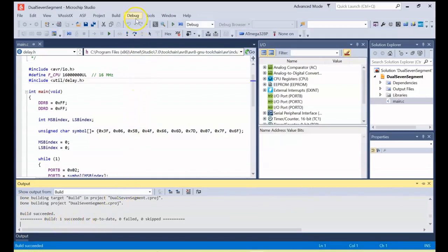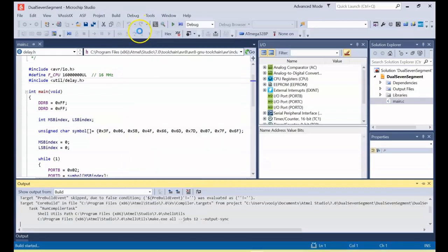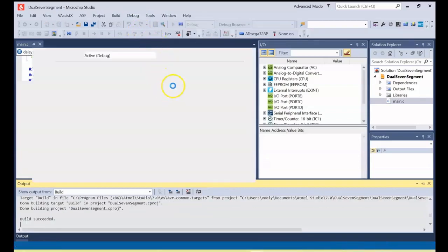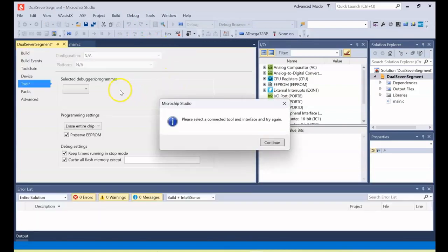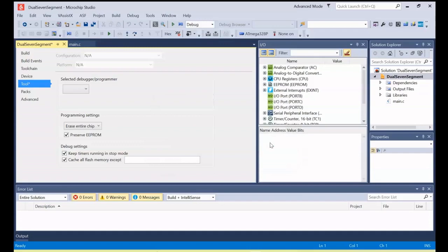All right, so what I'm going to do is, as per usual, go through this using single step first. So go to debug, start debugging and break. If you get this message, don't worry, click continue. Simulator, all right. If you see the asterisk here, you need to save it.